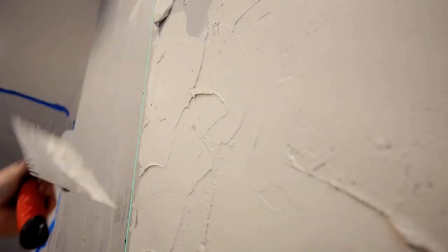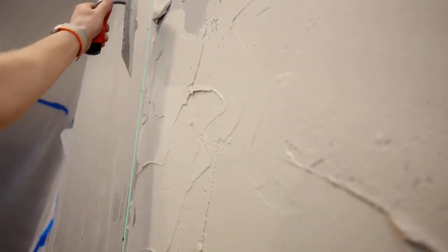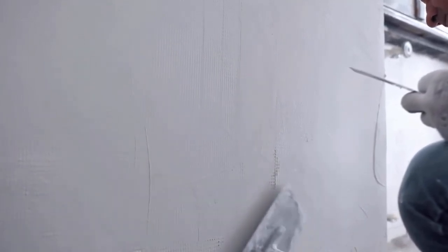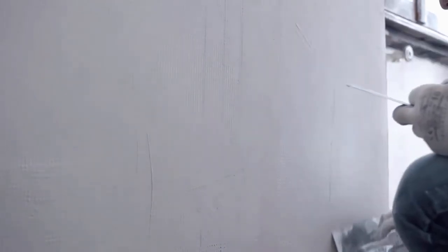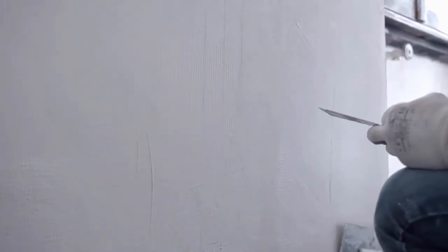And another thing, if we directly apply paint on the plaster surface, the consumption will be more, so that will not be economical. So from that point of view also, this wall putty is very much essential. You can say that without the wall putty or the base coat, it can be POP also, it is not desirable, or we cannot make that perfect surface finish. So that is why it is important.